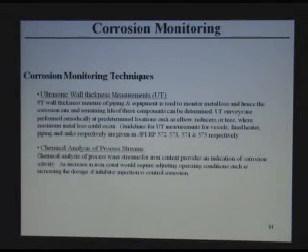take necessary action. There are API documents about how to make this measurement for vessels, fired heaters, piping, tanks. It is all given in API recommended practice 572, 573, 574, 575. They give you a good idea how to handle it, and it is useful not for us, but for operating people.